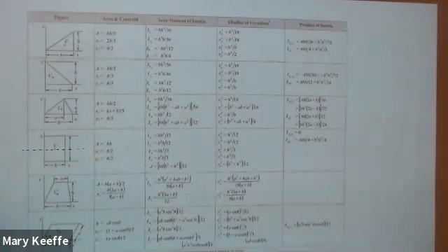So it would be around this axis. Now, a lot of times what they're asking us to do then is to find the moment of inertia around another axis. And so you always have to remember, you have to use I is equal to I centroid plus A times d squared, where d is the distance between the centroidal axis and whatever axis that you're asked to find the moment of inertia around. Okay? Everybody good?